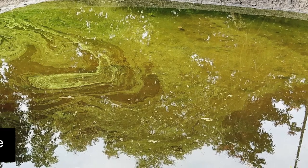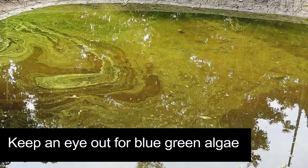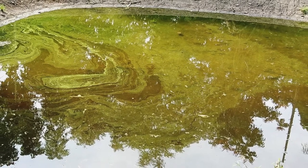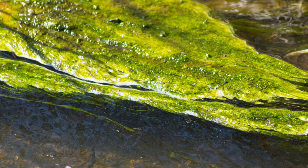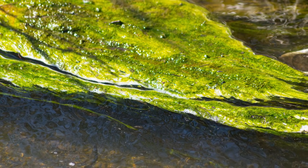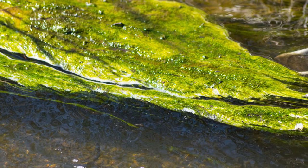Operators should keep an eye out for blue-green algae. Under hot, still summer conditions in much of Australia, facultative or maturation ponds may stratify, with the top surface layer of water reaching very warm temperatures, more than 30 degrees Celsius. Under these conditions, various blue-green algae can bloom and grow. In the worst cases, these algae can release toxins which can be toxic to personnel and animals if the treated water is recycled, for example, back to stockyards.